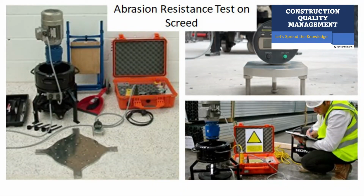The last testing method is abrasion resistance. As I explained, for abrasion resistance, the equipment has a plate underneath the machine which creates a rotational abrasion on the screed, and once the rotations are done at 2850 plus or minus 10 rpm, which will be approximately 15 minutes on the screed, the depth, the impact or a depression has to be checked using the gauge, and the screed abrasion resistance is evaluated.